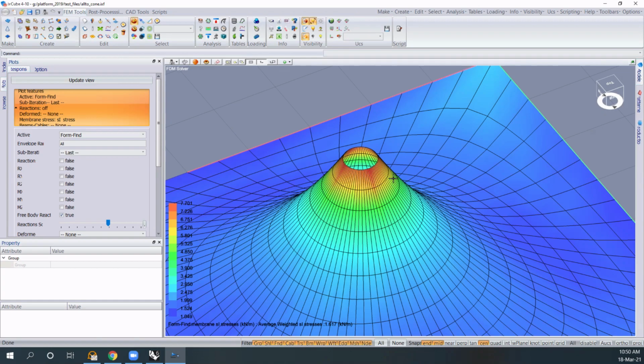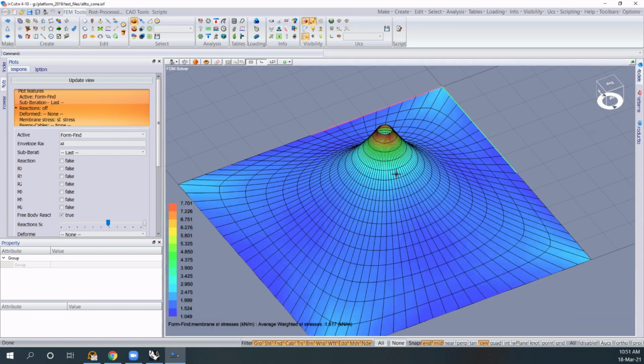Because the soap film would try to find an equilibrium in which the forces in all directions are the same. So the geometry of the boundaries of the ring and the square does not provide a chance, geometrically, to have similar or equal circles of curvature. And that's why it's not a minimal surface, and that's why the forces have to be different. If you force it to be like this, you could change the radius of the ring. If you provide more length, you could change the diameter of the ring, and then you could see how the forces would go down on the peak. Or another option would be to go lower with this tipping point, and then again the forces would go lower because the radius changes. Maybe this helps you also for your question.